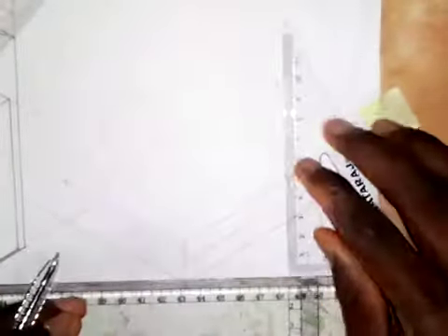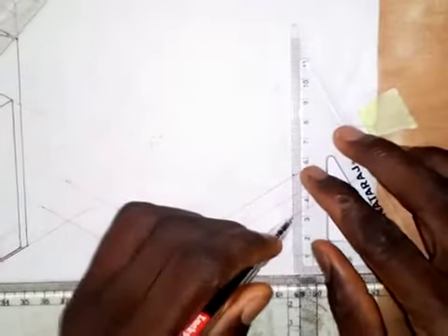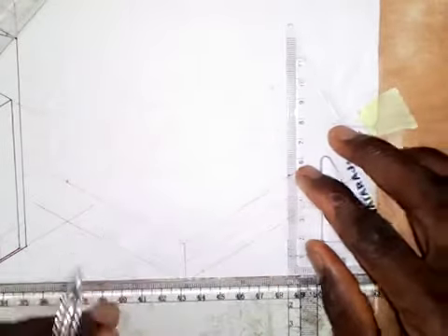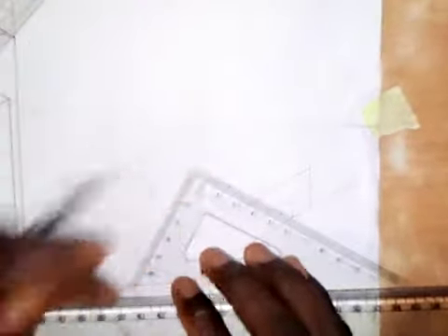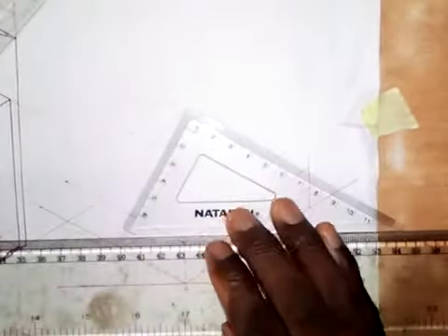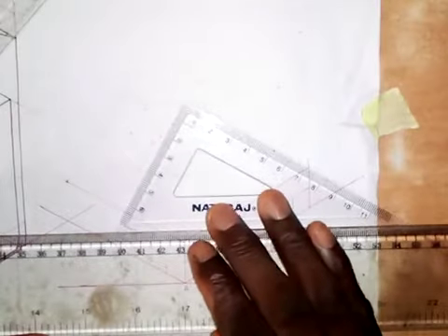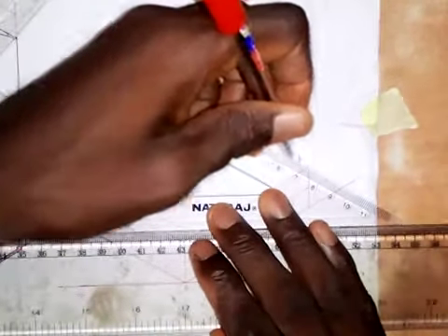So here I will transfer this to the other side like this. Then here I will draw a vertical line here. And here also I'll come to this point and draw a vertical line here. So this line I will need to draw from here. I will see a line that will go in like this at this point. So looking at this, the shape has come out. So all I need to do now is to transfer this. So I'll be transferring this point to this side like this.